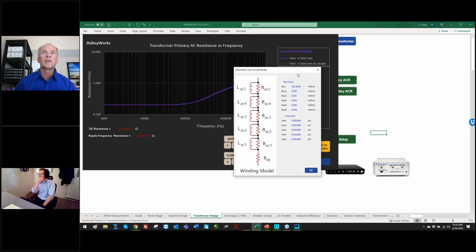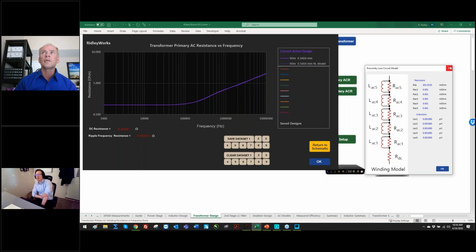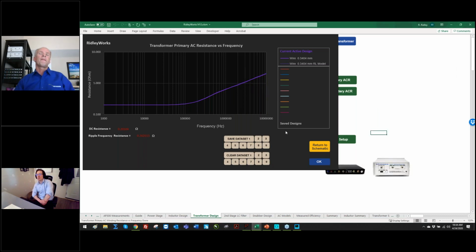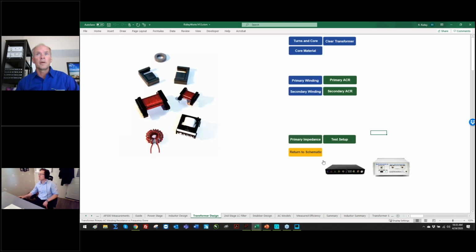So then there's a couple other questions here about temperature of the magnetic stuff. Is this all assuming room temperature, or are you changing temperatures? We can do all those things. We start at room temperature. The wire doesn't make a lot of difference. The coefficient on the wire is fairly small. And the cores? A couple of 100 degrees C, it matters, of course. When we look at the core losses, it will either use the 25 degree C model or it will use the 100 degree C model for extracting the core losses, because there's quite a difference there. Okay. All right, good.